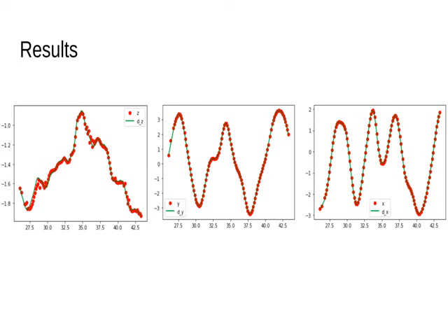Now, as you can see in our results below, these were fairly accurate. However, they did split at certain points. One of our running theories behind this is because the wings are not rigid, they're very flexible. As the aircraft flexes, as it shifts its structure, those aerodynamic coefficients will change dramatically. And because we used a fixed value, we told the optimizer to assume that this value would never change over the course of the flight.